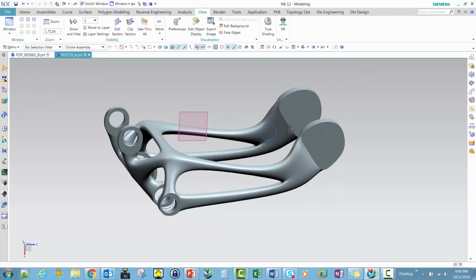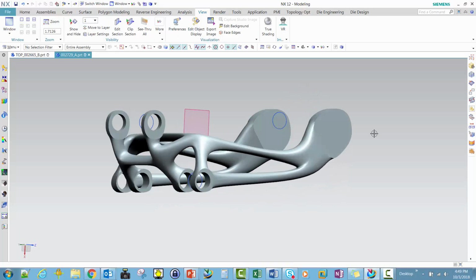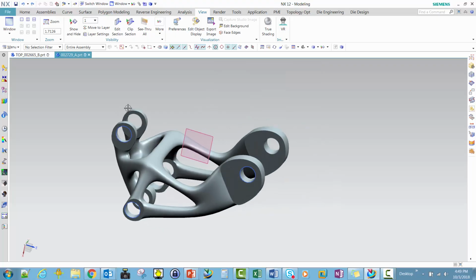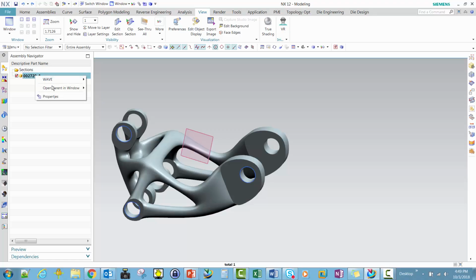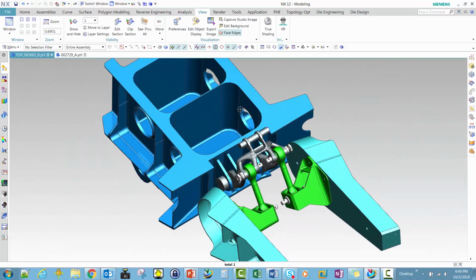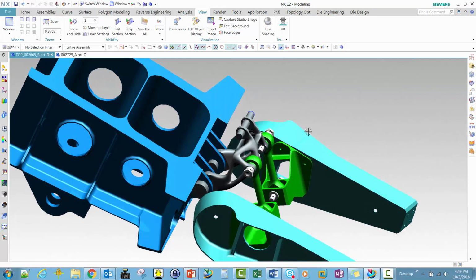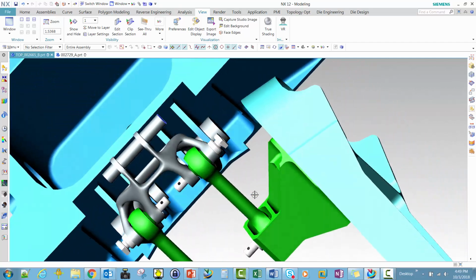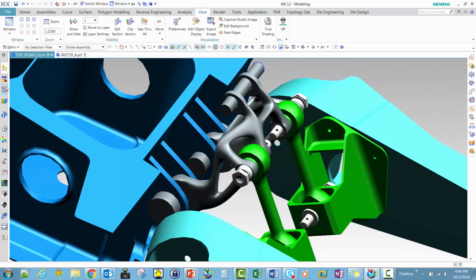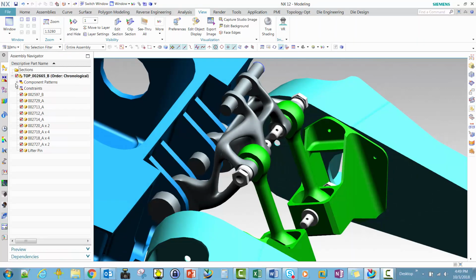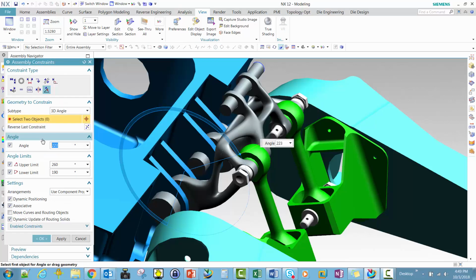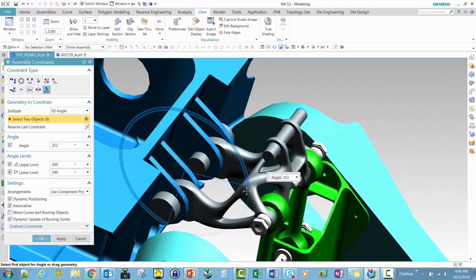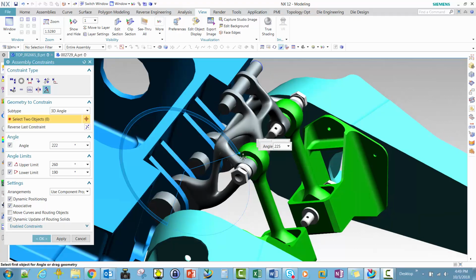Of course, these holes don't update because they no longer go through the part. But we can update it, and not only can we update it, but this is a good CAD model, so we can go back into the assembly and we can see our part. There's our new part built right in the context of the assembly, reverse engineered in minutes using realized shape, and we can even show that it's a good working part. So there you have it. That's reverse engineering a faceted part using realized shape.